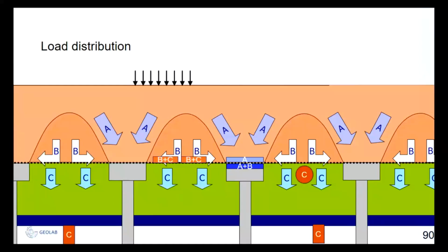Then in the case of our experiments, we also measure the total load on the steel stiff plate underneath the soft soil. The pressure in the foam cushion, C, should be the same as the total force underneath the foam cushion. So different ways to measure the load distribution. So C is measured in 3 ways. It's a total pressure cell underneath the reinforcement, which actually seldom gives good results. We measure the pressure in the soaked foam cushion, and we measure the force underneath the steel plate under the cushion. And those two match very well.